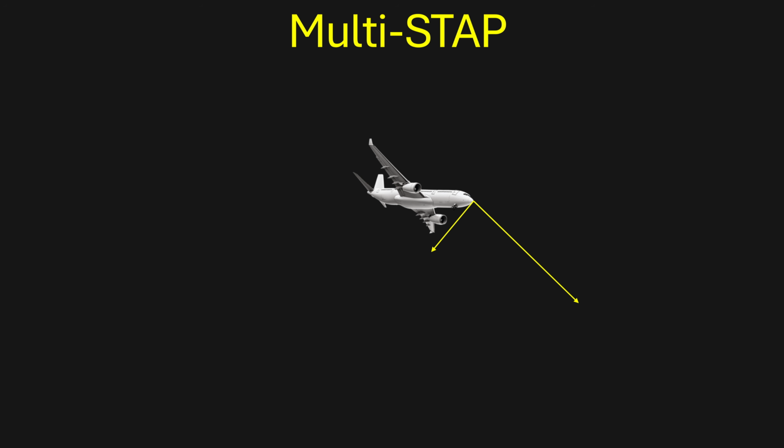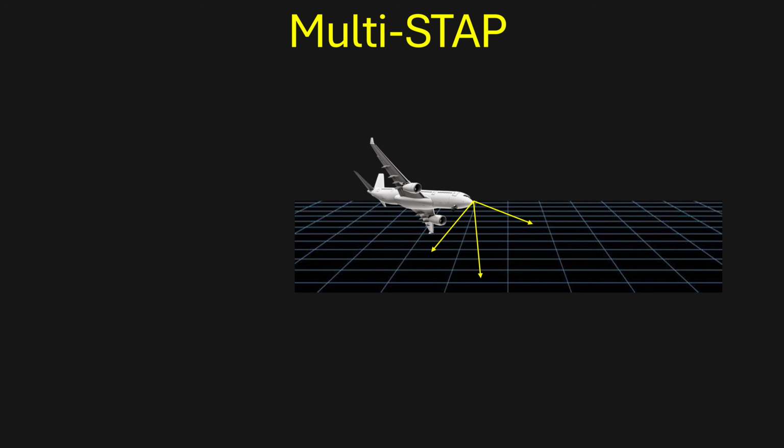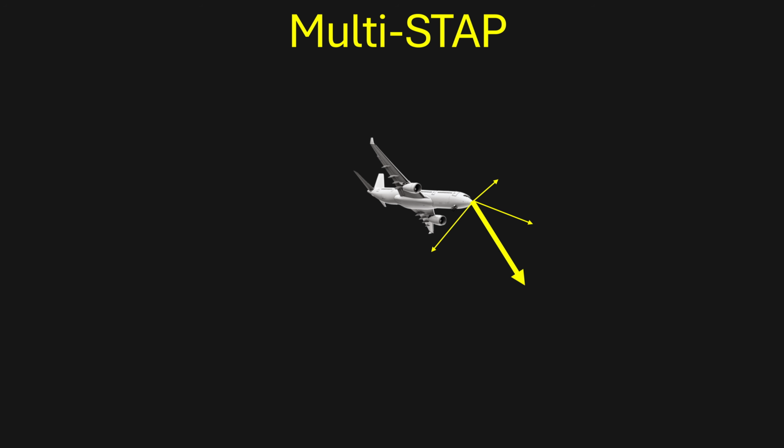Next, we have the concept of a very large STAP constellation that would have detections from targets on multiple platforms at the same time. If you can match locations from two detections, you will also have two radial velocity measurements that are linearly independent. We can then project this onto a level plane, or you can have 3 independent STAP detections and you'll have a certain 3D motion for your target. The same applies for along-track interferometry.